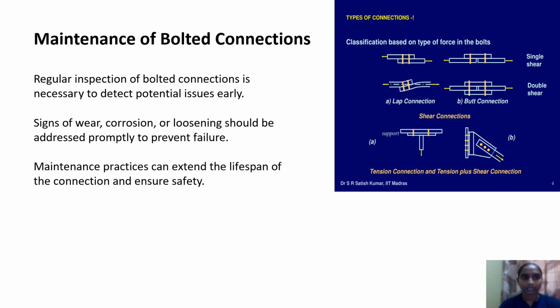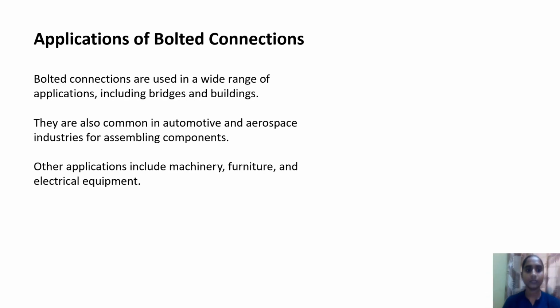Maintenance of bolted connections. Regular inspection of bolted connections is necessary to detect potential issues early. Signs of wear, corrosion, or loosening should be addressed promptly to prevent failure. Maintenance practices can extend the lifespan of the connection and ensure safety.